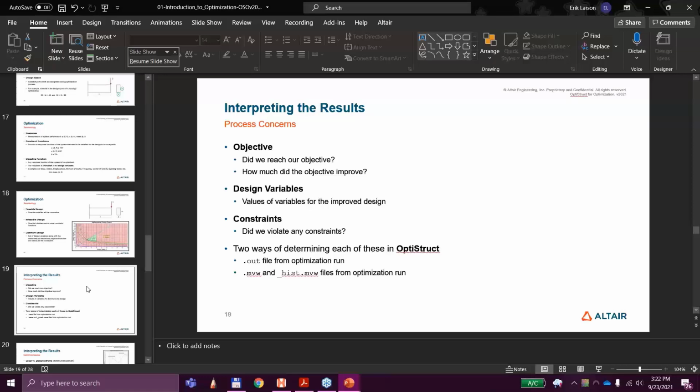changing the current design. If I come up with an optimized design on a control arm and the part only ends up being a half an ounce less mass, is it going to be worth the hundreds of thousands of dollars I have to put into changing the tools, the time down because the tools are being changed to get just that half an ounce savings?